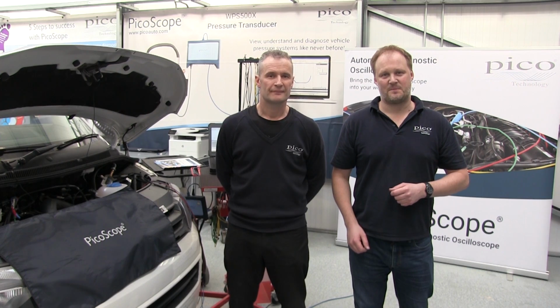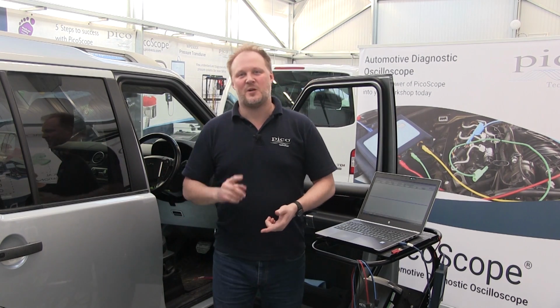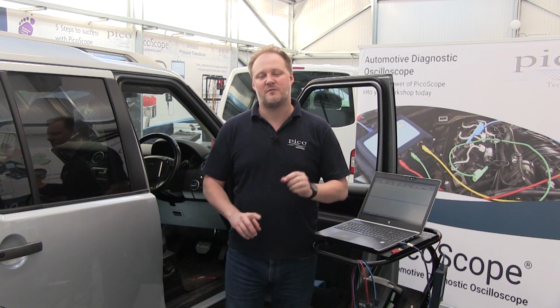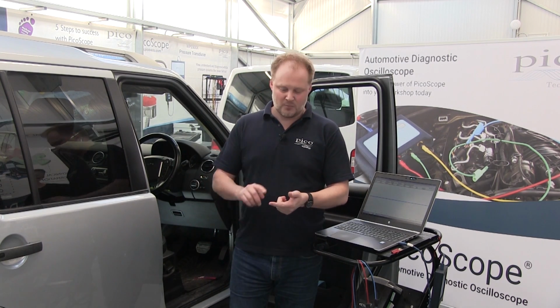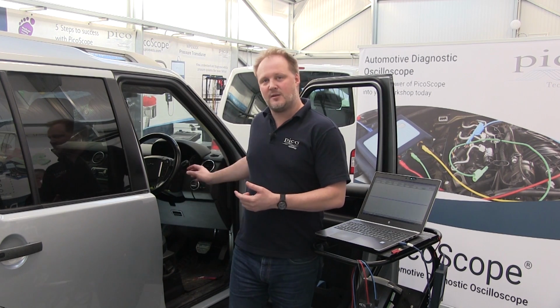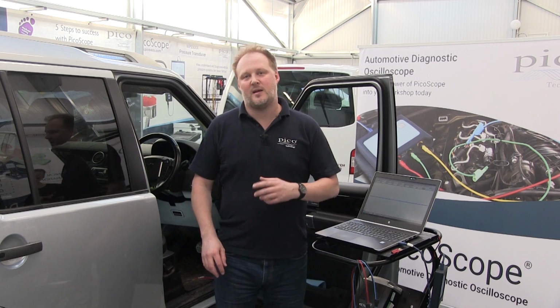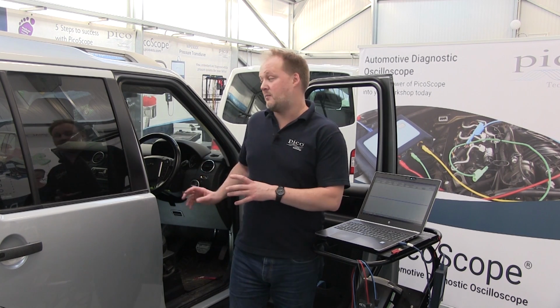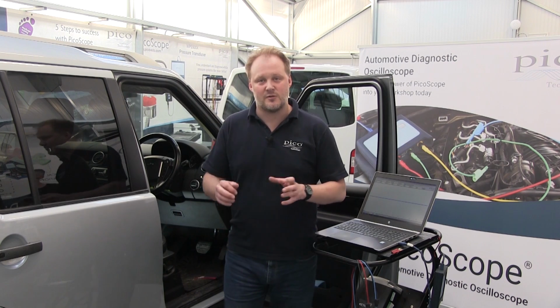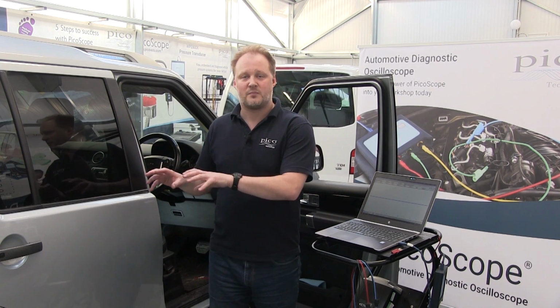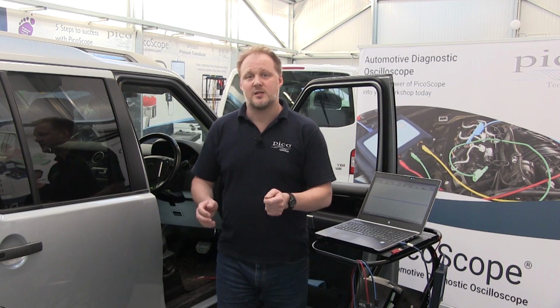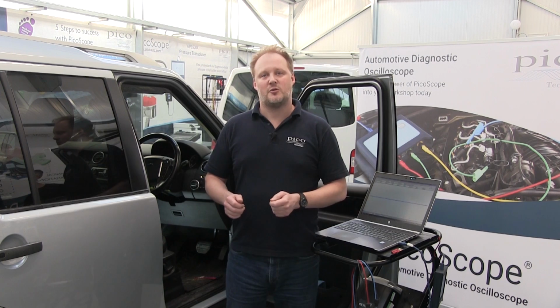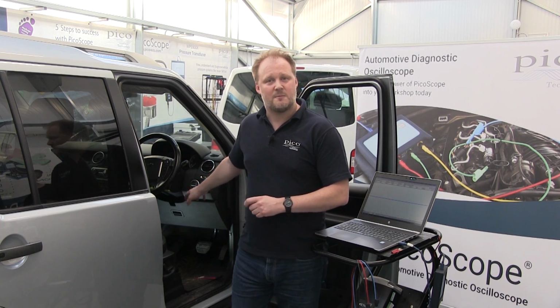Lovely. So we'll begin by looking at the different ways we can connect to a vehicle. So in this part of the presentation, we're going to look at different connection methods and different ways you can access your CAN bus. In the first method, we're going to use a pinout at the diagnostic link connector. In the second method, we're going to connect at the same place, but we're going to use a breakout box. And then in addition, in this video, we're going to show you how to connect directly at an ABS control module. You might need to do this because not all vehicles give you direct access to your CAN buses at your diagnostic link connector.